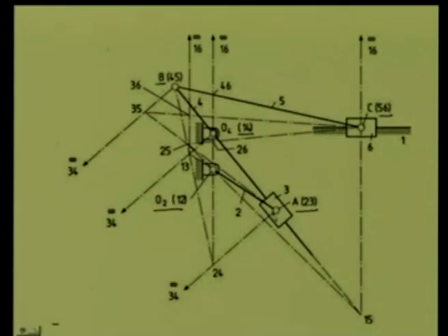Corresponding to the prismatic pair between 3 and 4 along this O4A, we have 3 4 in a direction perpendicular to O4A and lying at infinity. So all these parallel lines 3 4 lie at infinity along this direction. Similarly, 6 is in horizontal translation with respect to link 1. So the relative instantaneous center 1 6 is at infinity in the vertical direction. That is, on all vertical lines I can say 1 6 lies at infinity.